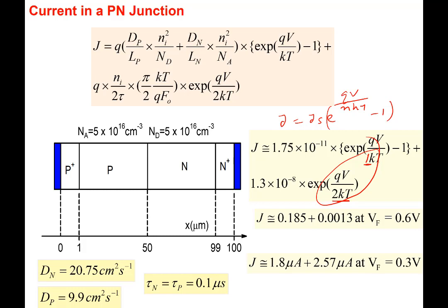Yes. But sir, at higher voltage, that graph still shows some deviation. Oh, that is a different part. We have not gone to that high voltage. We are saying it's still the low level injection approximation. So here, this is a case of going from very low to medium voltage, and we end up with n between 1 and 2.